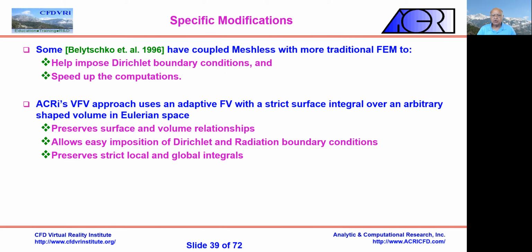Most of these meshless methods do not ensure that, when you're dealing physically with your integrals, each integral eventually would be a control volume, though virtual, and that the total sum of these volumes, which are used for the integral of these governing equations, all add up to the total volume of the system. Many of them don't. Similarly, the surfaces that connect them do not necessarily add up to the same as the external boundary surface if you eliminate the middle surfaces.